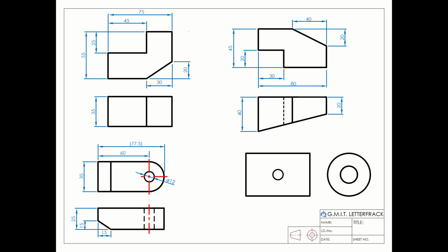But if you were making a piece that wasn't necessarily square, let's say it was four-sided but maybe tapering, you could actually give them the dimension for the diagonal, so that it should be this measurement when you check it.